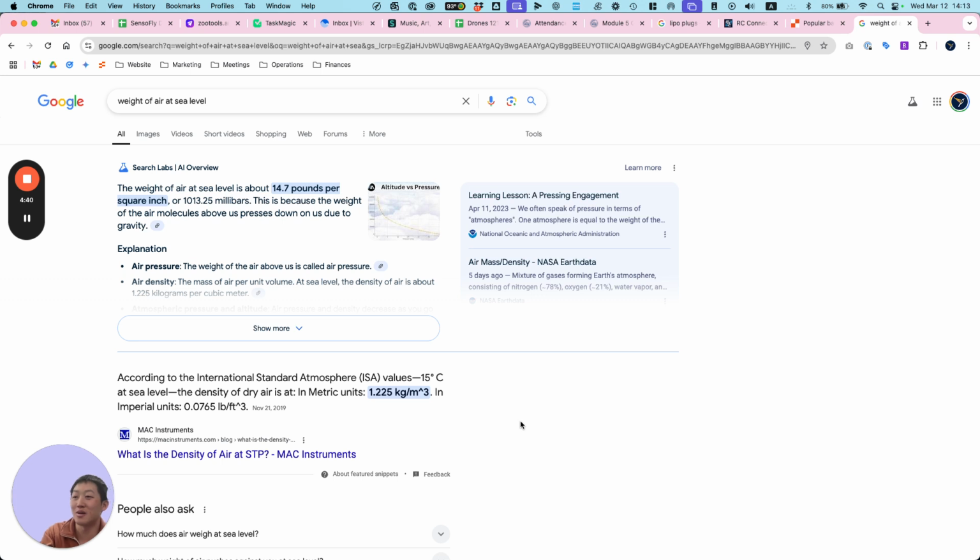So during the summer, when the air is very hot, is it less or more dense? Less. It's less dense, okay? The planes can't generate enough lift, so sometimes they may ask, hey, we need some volunteers to take the next flight because it's too heavy to take off on that short runway. So it's the same effect having hot air versus high altitude air. But anyways, that's density. Planes like drones need dense enough air to generate lift.